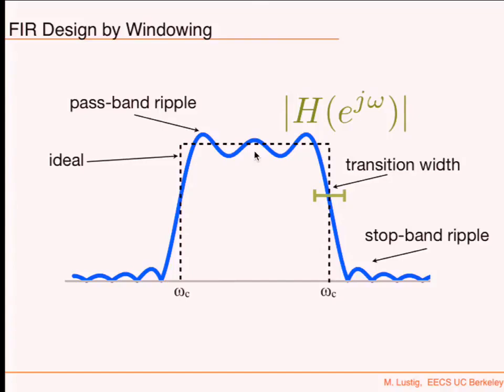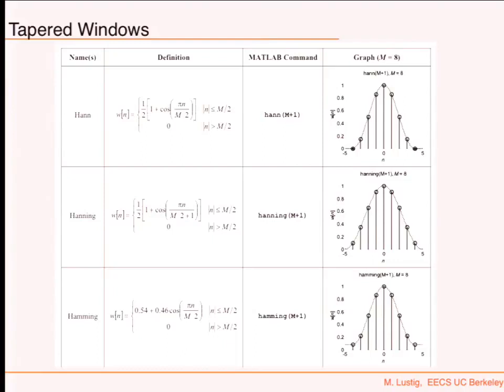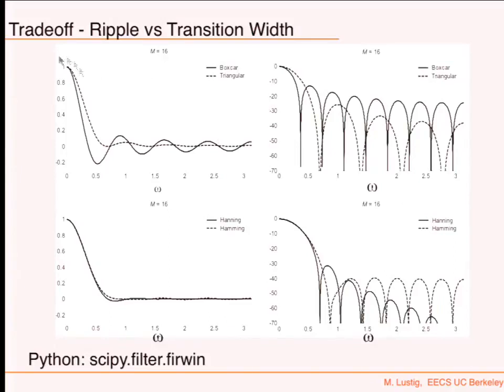So I can kind of move on, right? Here are slides from the lecture on frequency analysis. I can use a Hann window, I can use a Hanning window, I can use a Hamming window. I could tell you all the story about all these windows, but I'm not, because I already told you them. The good thing is that for different windows, you can see how rapidly the window decays and how much ripple you get, and so on. So for your particular application, you can choose the right window that will be best for your particular number of taps, for the minimum number of taps.